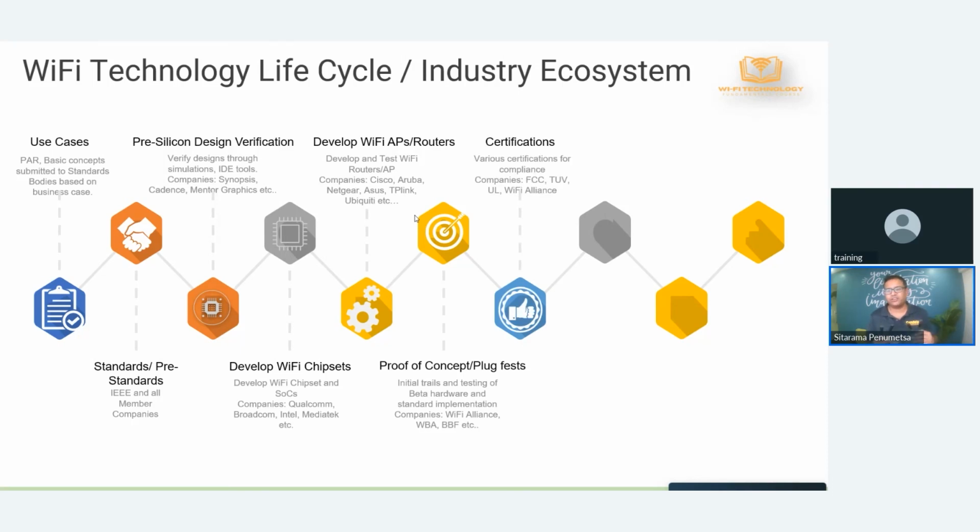As you build this product, you have to go through FCC certification to make sure that this radio is complying to the requirements. Remember, when I said these access points use unlicensed frequencies. What that means is there are some restrictions. They cannot transmit at more than a certain power, so that you give other people a chance to reuse the frequencies, right? Which means that you need to get a certificate saying that yes, this particular access point or router indeed cannot transmit at more than so much transmit power, and for that you need a certificate. Similarly, you need UL certificates to make sure that it operates at a certain temperature level and certain humidity levels, and it doesn't have any spurious emissions. It doesn't emit signals in other frequencies that it's not supposed to use. So lots of certifications that we need to go through, right? And there are certification bodies for that.